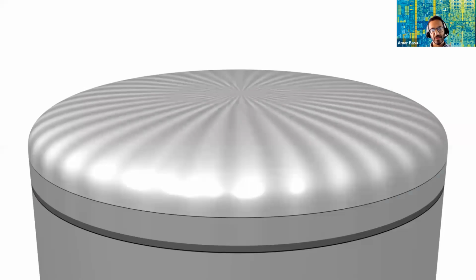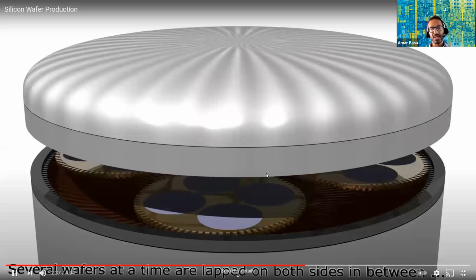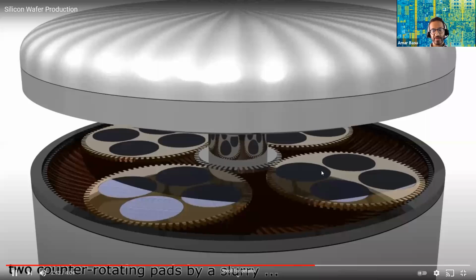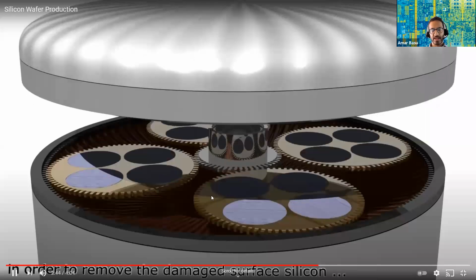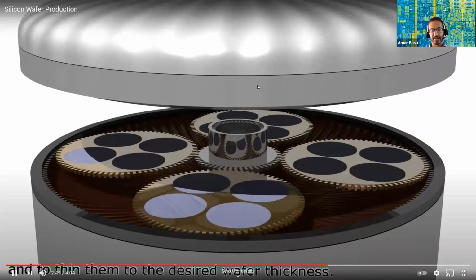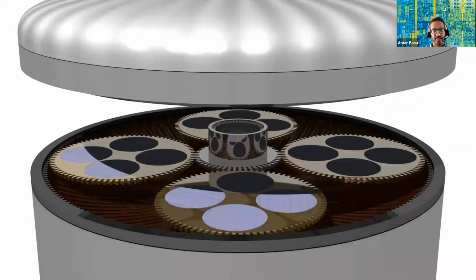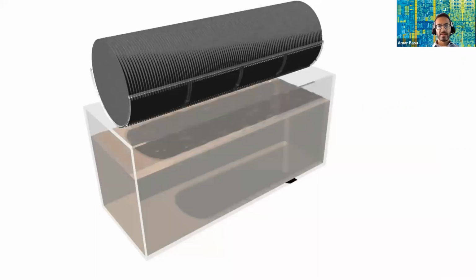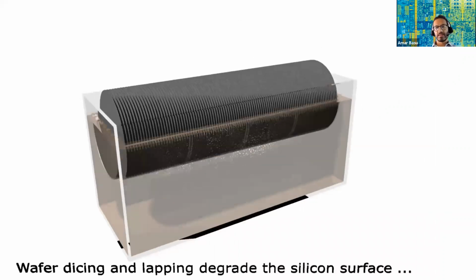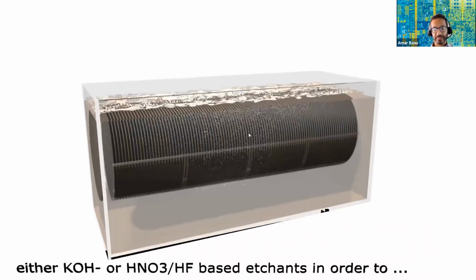After you cut, you're going to have rough surfaces. So there's this process called CMP, chemical mechanical polishing, where these wafers are put in these rotating discs, and there's this cap that comes out on top that has etching chemicals on it and also mechanical movement that is basically grinding the silicon wafers down and polishing them so that you have a very smooth finish.